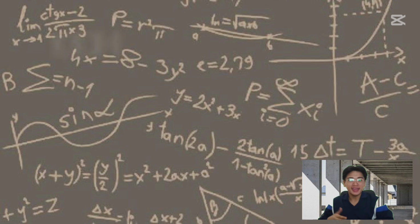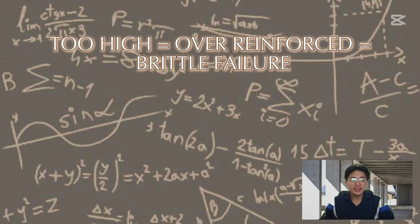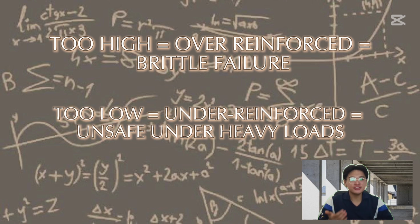If it's too high, it is over-reinforced, which can lead to brittle failure. If it's too low, it's under-reinforced, making the beam unsafe under heavy loads. That's why engineering calculations are so important. They ensure safety and efficiency.